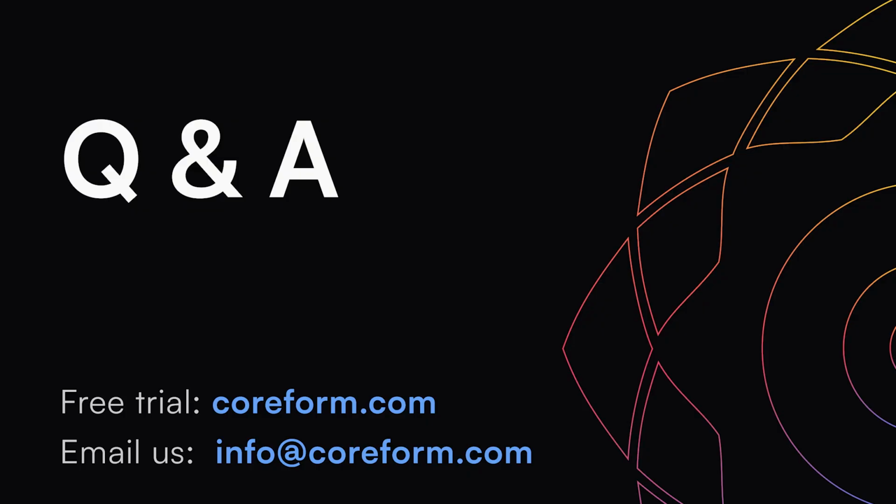Is Coreform IGA compatible with all material models available in Abaqus Standard? No, there are a few material models that are not supported by UEL MAT. I don't know them off the top of my head. My recommendation is that if you go to the Abaqus documentation and look for UEL MAT, it'll provide lists of things that are and are not supported. I do believe that it's fairly limited on the things that are not supported. I think there's a concrete crush model that maybe is not supported.